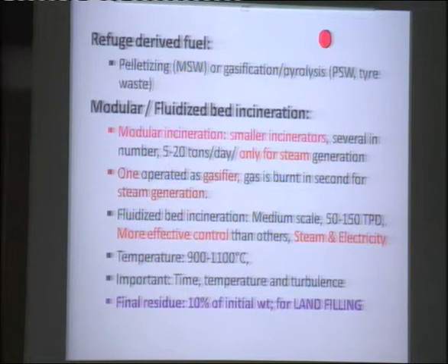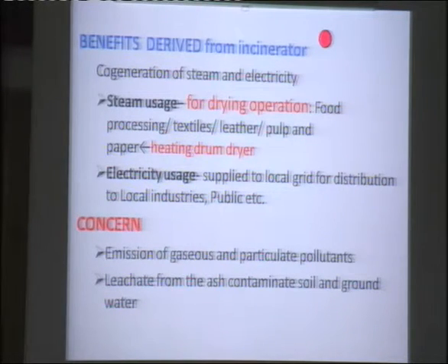Modular incineration. There are many incinerators which are built in very small units, only 5 to 20 tons per day, and that is used only for steam generation, because it is not economical to produce electricity from there. So only steam can be generated. Under that condition, one is operated as a gasifier. The gas produced is burned in the second chamber, and the steam is produced, and that steam can be utilized for different purposes. We will come to that a little later. It can be utilized in different industries.